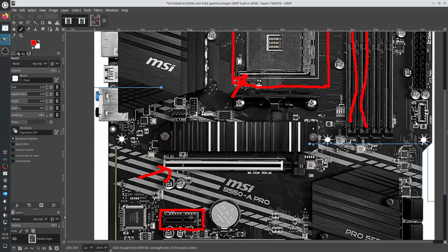So this is a subset of pins. In here you can see all of the pins on the top row and on the bottom row. The same thing exists in here. And then there's this separator. So all of the extension cards that you can put in slot 2, you can also put in slot 1, but it will not use all of the PCIe pins. It will use just the ones that it can use.